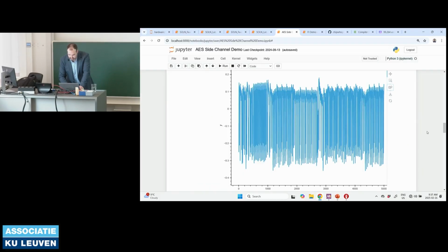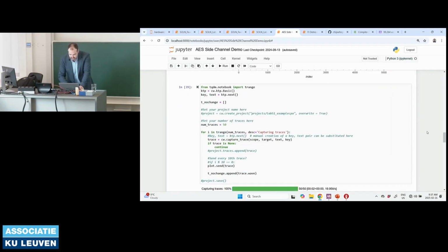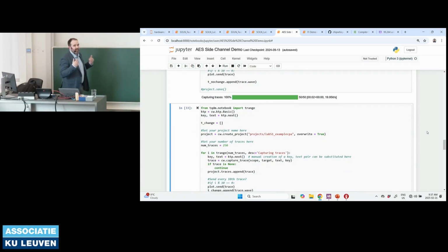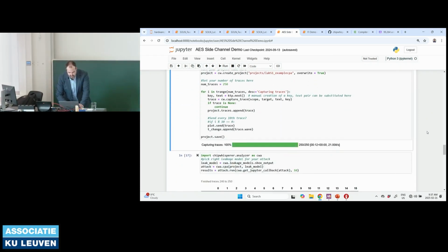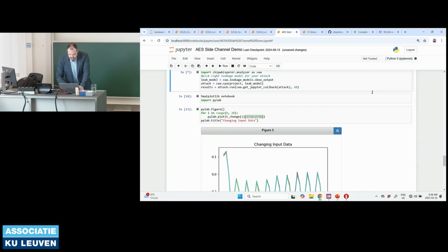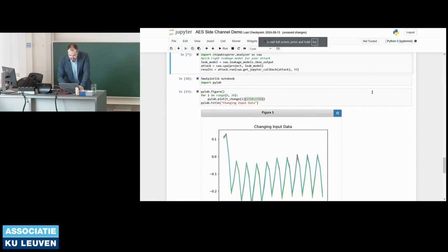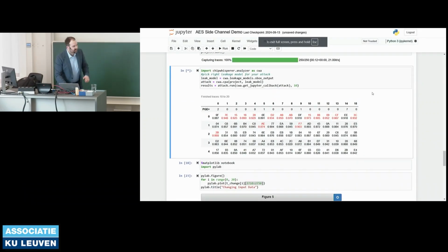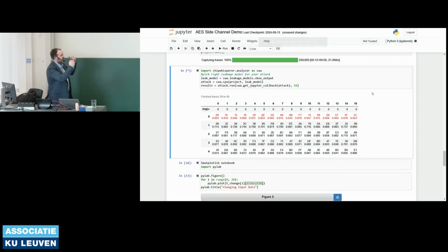So the interesting thing is that AES, if you were to brute force it, is sort of like a heat death of the universe timing. But if I run this little attack here, the correct key is known in red. So you can see it very quickly highlights the correct key. And there's a number below it, which is the correlation.